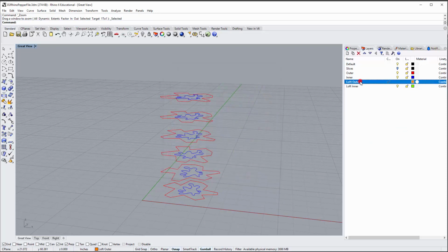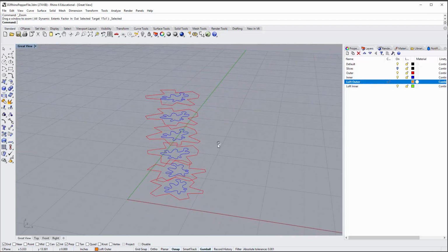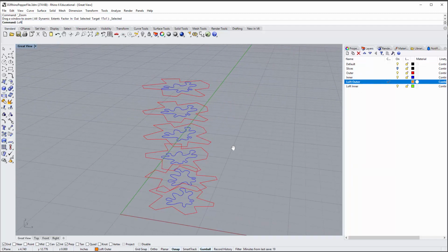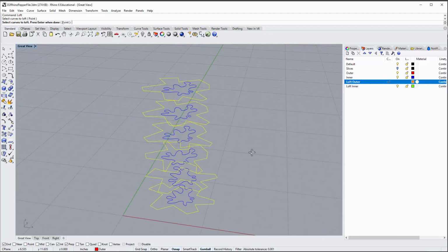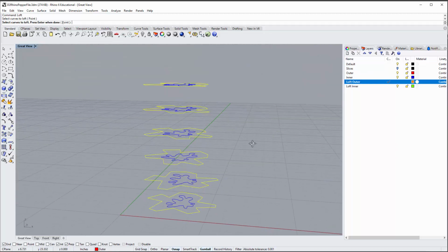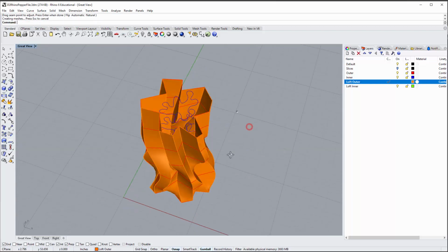Okay, I'll make it active when I do these commands. So double click here so the tick box or the check mark is next to it, right? So loft outer, and so the loft command, right? And in my case, I can actually just get them all together by doing that, the selection set from the lower right corner. Everything it crosses, it will select and just run the loft command, enter, enter, say OK, right?